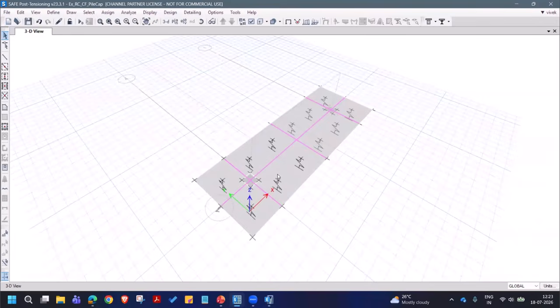So in such cases, you can apply a small area spring to the pile cap that will contain the rotations. You can see large deformations in some cases, so you can overcome that with those. That will not affect the design significantly, but those are the alternative ways available to control the large deformations. Okay, so in this case, this is well supported in both directions, so you don't require such.